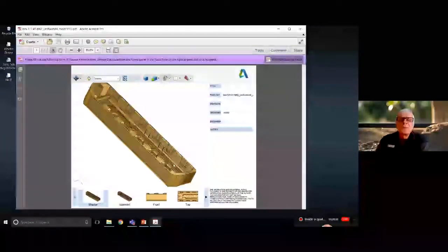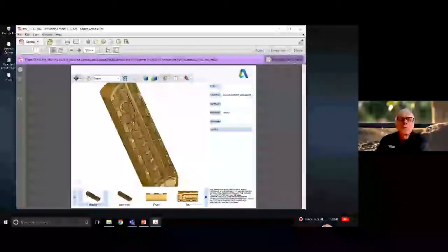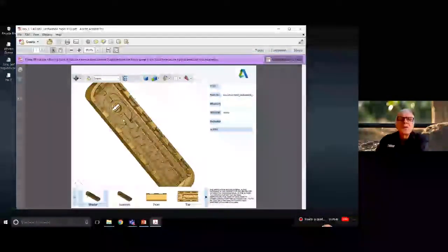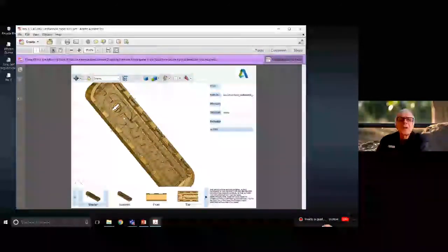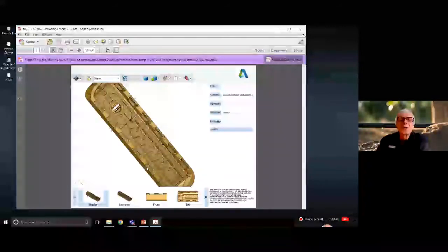Now what I'm going to do is show you the top of the range dripper, the UniRam. That round circle there is the inlet to the dripper, and from there it's got a diaphragm, and resting against this is the flow path labyrinth, and there's another flow path that goes on top of it.